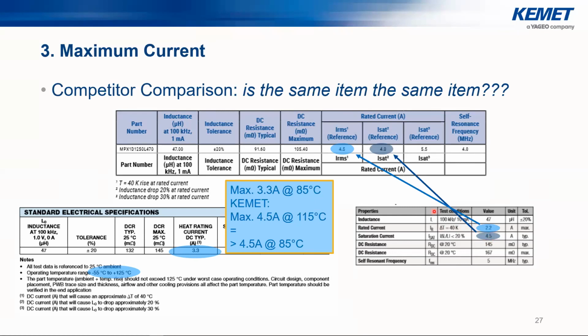I don't care about this one because this is real important. The maximum current is somewhere given around, depending on your application temperature, at 5 amps, maybe 4 amps, maybe 4.7, I don't know. But with this item, you will never get higher than 3 amps, never, it's not possible. So here, the same looking item is worse.